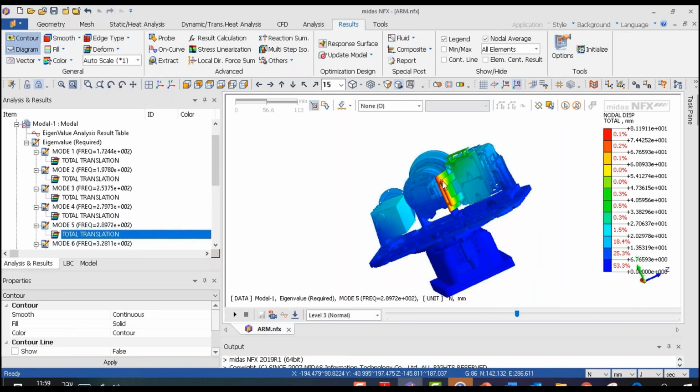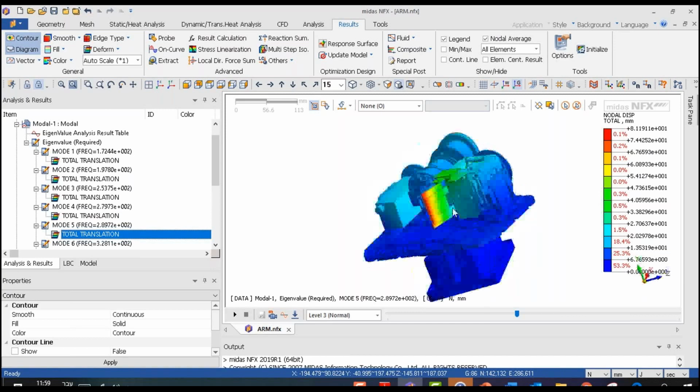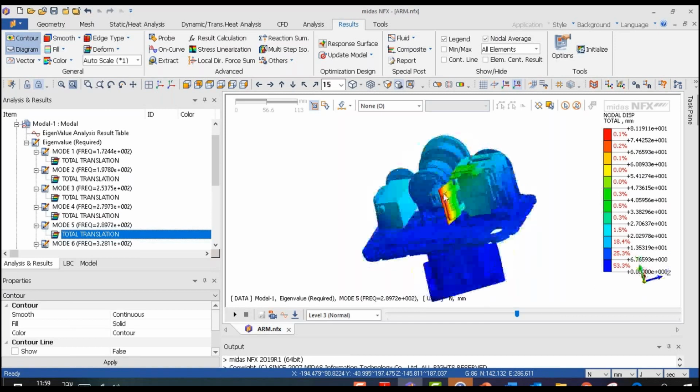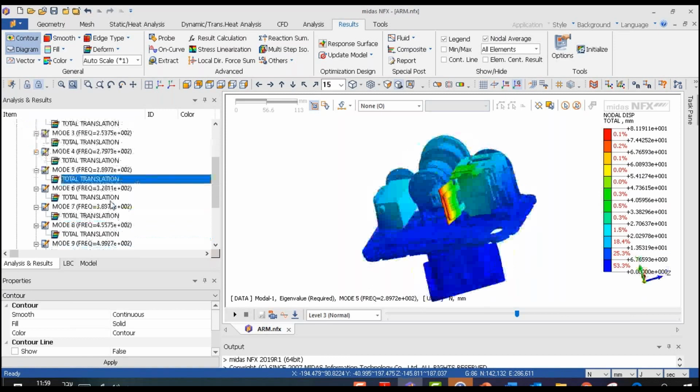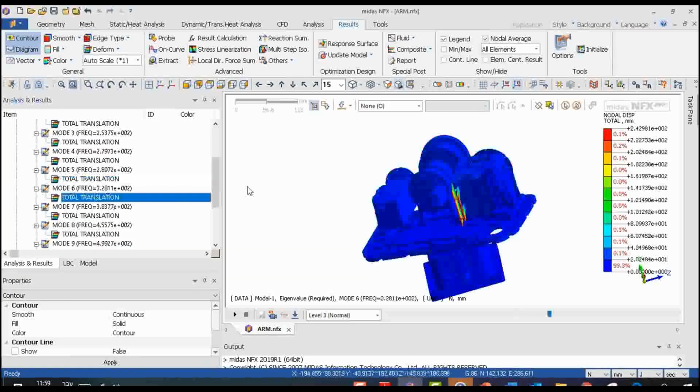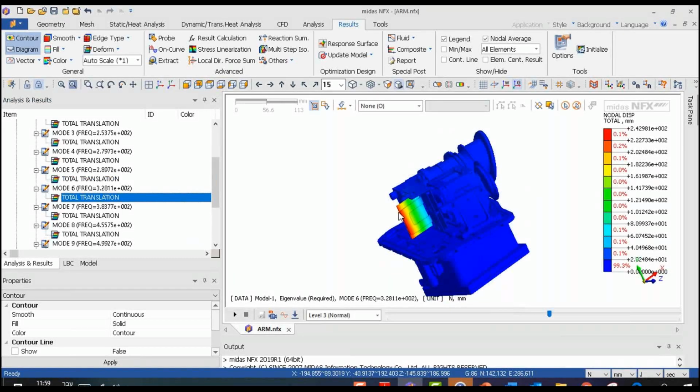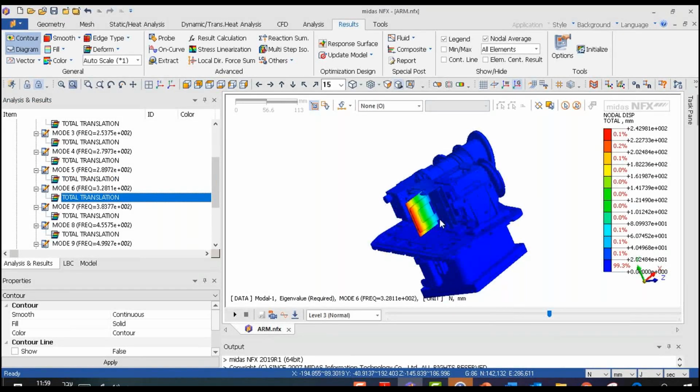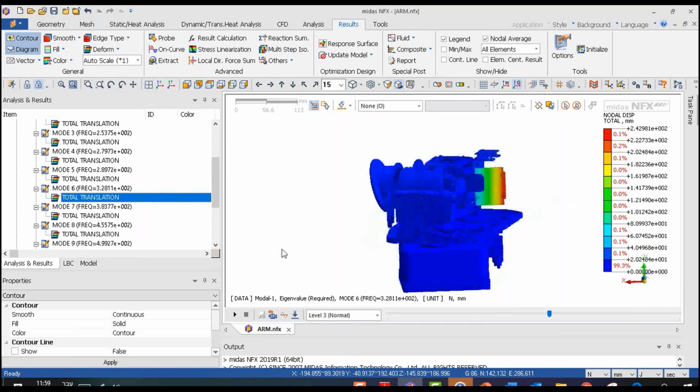We see here that the digital PCB has the biggest deflection. This is the excitation here in the 5th mode. The 6th mode also excites this board and the mounting bracket which holds it. Those are the six sensitive frequency modes, where the system has a resonance at these frequencies.